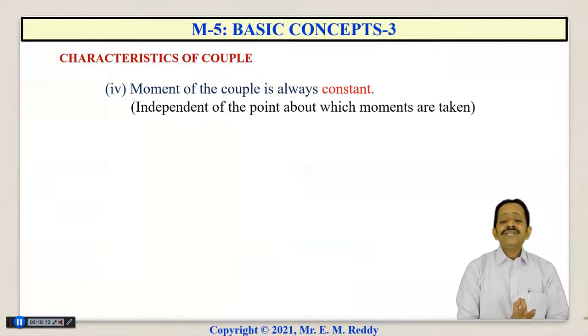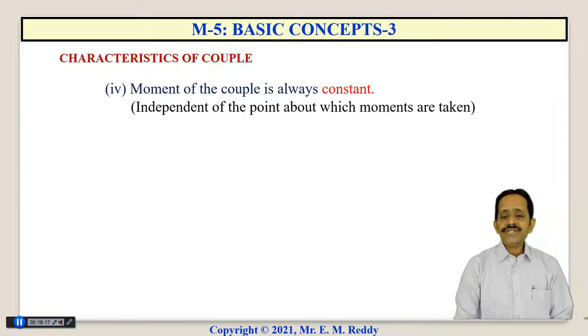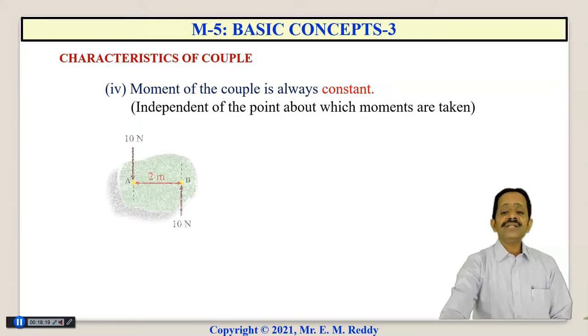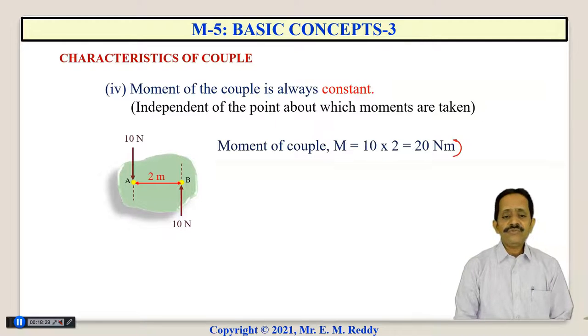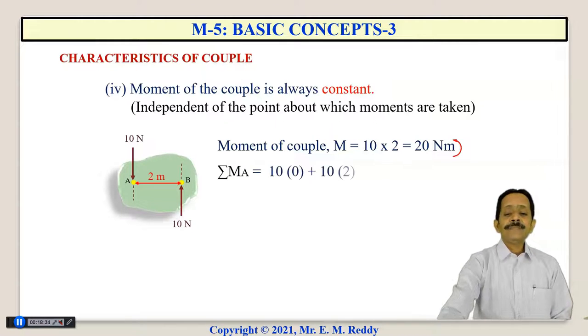Moment of the couple is always constant. It is independent of the point about which the moments are taken. Now consider the same example. Here the moment of couple is force into perpendicular distance between the two forces, that is 10 into 2, 20 Newton meter. Sense is anti-clockwise.